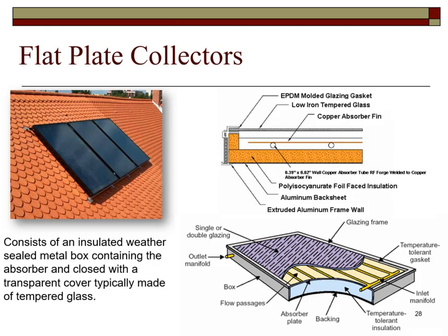The absorber plate is usually made of copper or another material that has a high thermal absorption and conduction rate. This increases the actual collection area and conducts the thermal energy toward the flow pipes and the fluid. Most collectors are constructed of extruded aluminum for weight purposes. Most installations are on a roof, as well as for their ability to withstand being outside all year long.